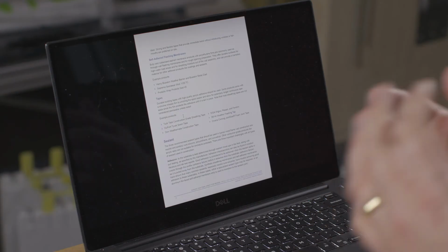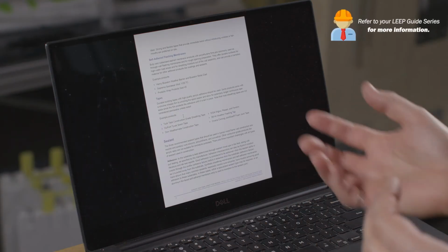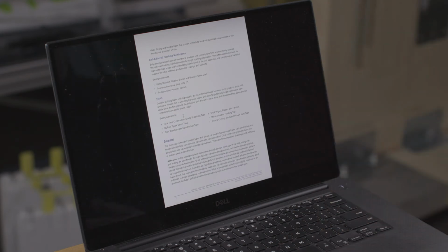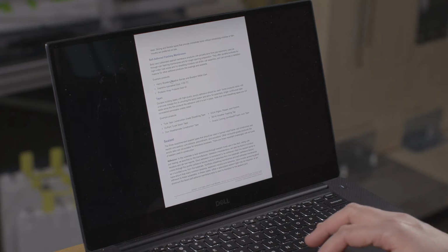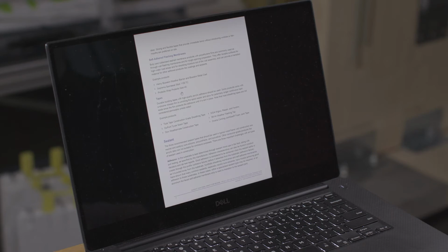And so what you're looking at there is adhesion, the workability, how tough that material is and how it's going to stand up to the details. The big thing is, with a lot of these self-adhered membranes and flashing membranes, do they need primers or do they not? And so following the manufacturer's recommendations for that is critical. Example products: Blue Skin, Soprema's Sopraseal Stick, Protecto Wrap, Protective Seal, and there's dozens of other peel and stick products that can be used in this application.